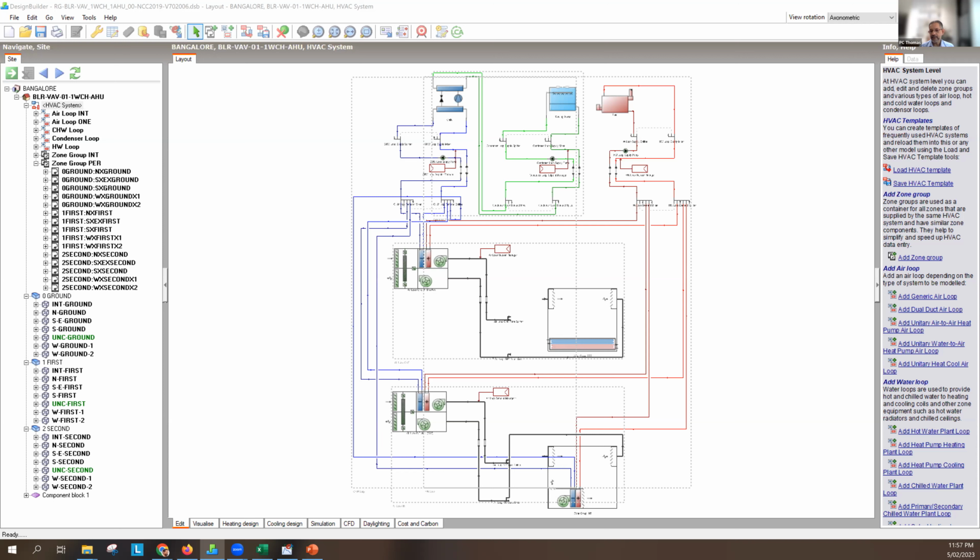And when you have a direct expansion system, you are connecting these joints on site. Okay. Unlike a chiller where everything is inside the chiller, it's factory made, you never see the refrigerant circuit. So it's not a question of if that refrigerant will leak, it is when that refrigerant will leak. Now, what makes it worse is many of these refrigerants are blends. They're not a single refrigerant.